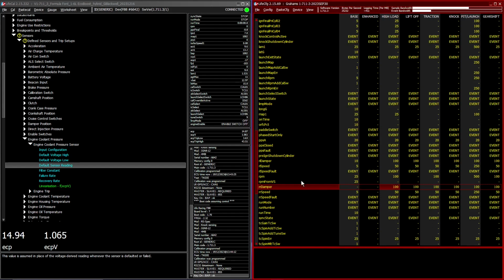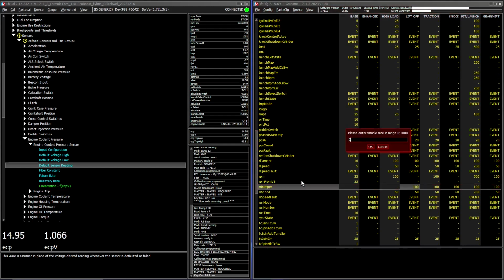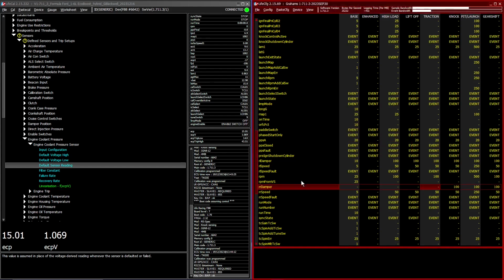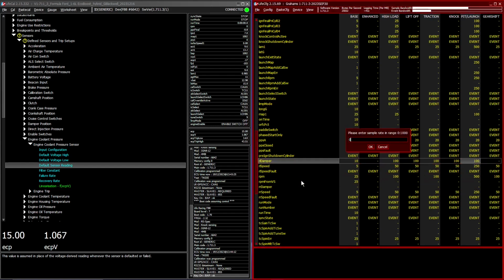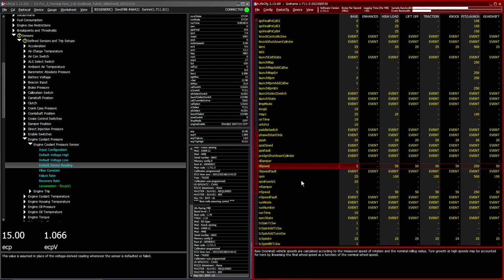So I'm going to set all these to 0. Right rear damper, that one there's a 0. I just press return twice, it clears it. And then we want rear and left damper, which is that one there, so 0. That was taking up quite a bit of memory because it's recording the damper positions for both those dampers at 100 times a second. So that's now off.